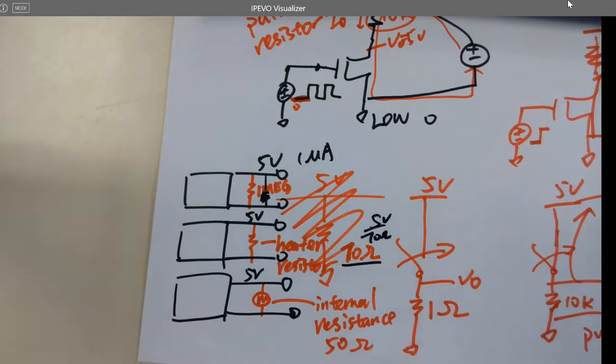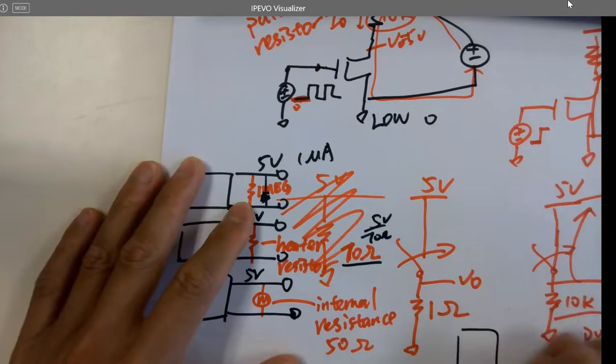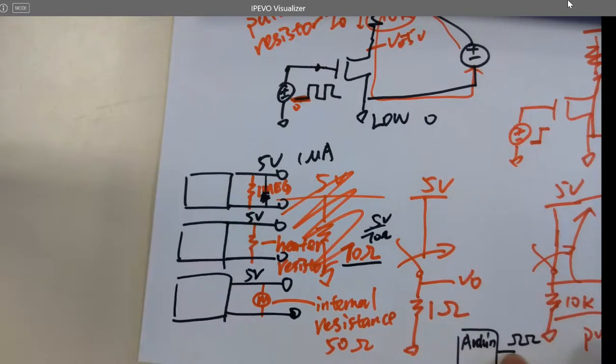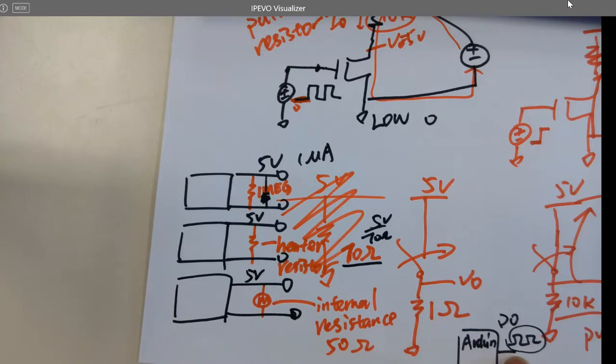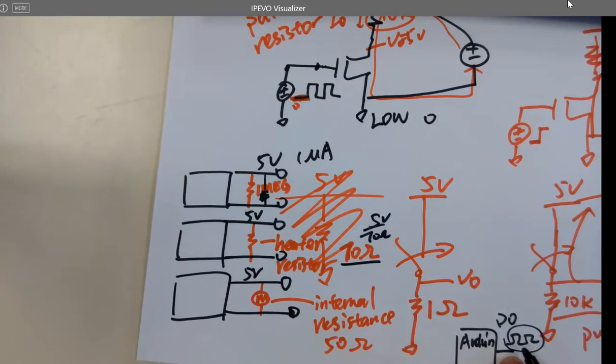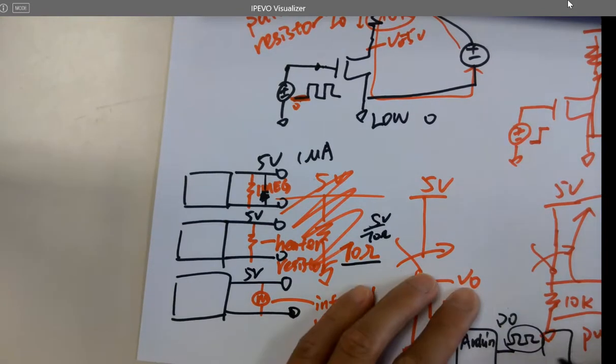The driver can rebuffer that circuit because it has all the connections to the 2 rails. So whenever you drive it, use your digital pin with Arduino. Anyway, when we are using a digital pin like D0 from the Arduino, are these digital signals powerful or not powerful? Do they have a lot of current in here to drive a heavy load? No, these are just really light, really not powerful digital waves. So what you need is to connect the driver. Why does the driver make a difference here?